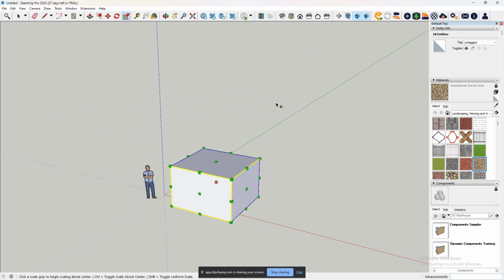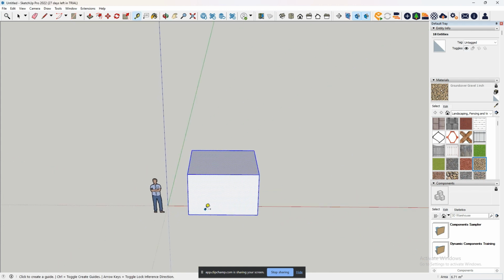Now moving on to the tape measure tool, which is this yellow icon here. This is very useful for, obviously, measuring the dimensions of your object. It is as simple as locking on to a specific point of your model, clicking it once, and then wherever you move that tape measure, as you can see in the bottom right hand corner, it's going to start giving you the dimension you want. So I can either stop this if I want the midpoint, it tells me what it's going to be, and you don't want to click it yet, so I still have only clicked it once,